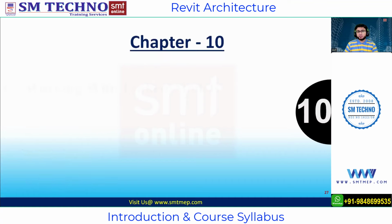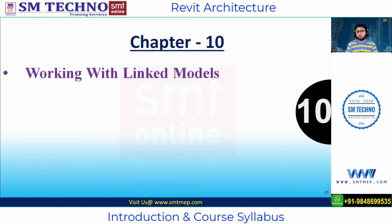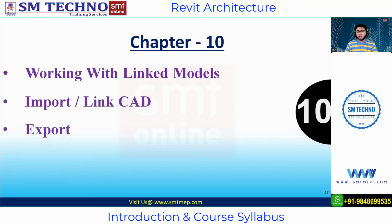The next chapter 10, where we are going to work with the link model. As Revit is software from Autodesk, we have got different other software also from Autodesk. We can export, link or import from one model to another model. That is what we are going to see over here. And again, how to import or link the AutoCAD file. We can even link other services drawings of another project. The same thing, how to export.